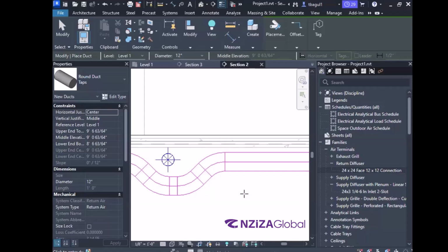Now go over, zoom in and remove the elements. In case your unions are giving you issues connecting, make sure you delete the unions.